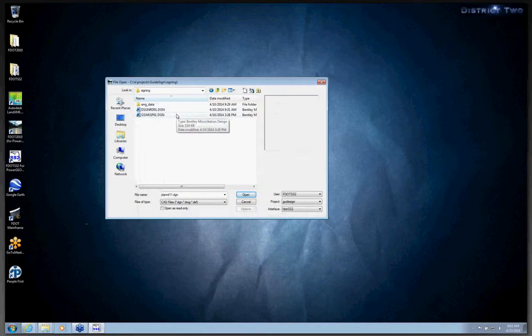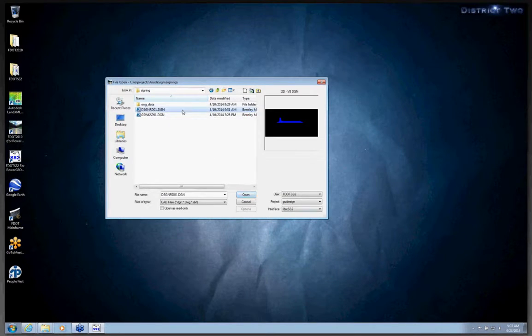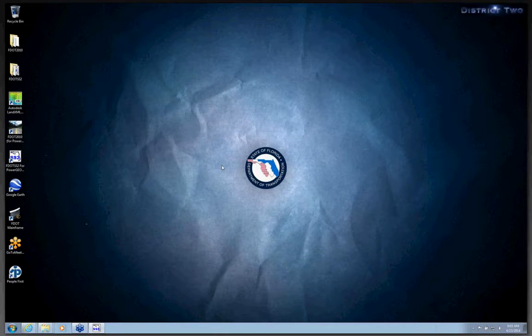Once you create the project, usually you will not have a guide sign file set up. The reason for this demonstration is very important: the guide sign file is unique, unlike a lot of your other design files, where it needs a special seed file.